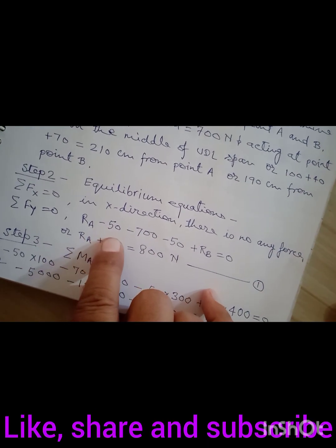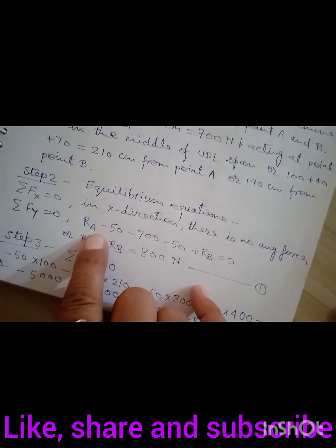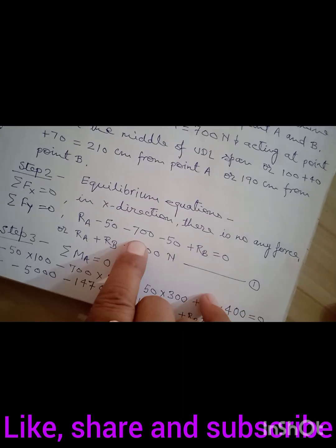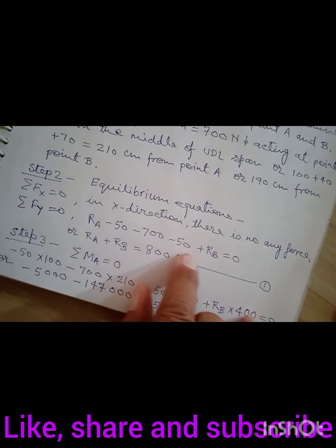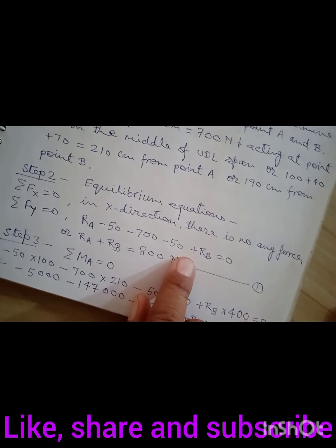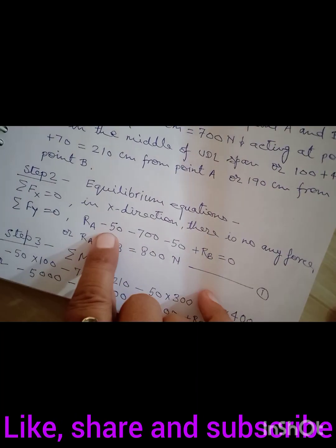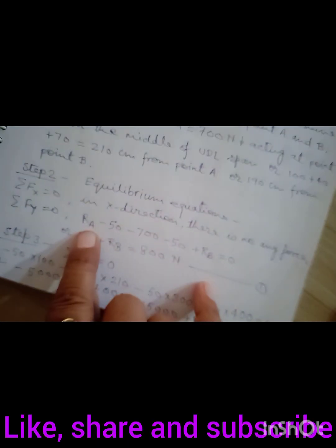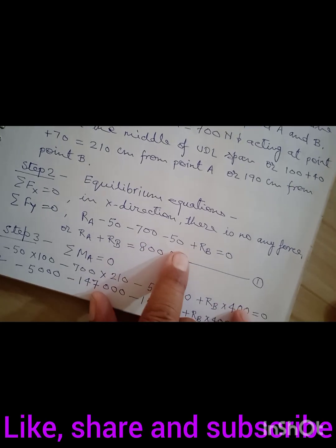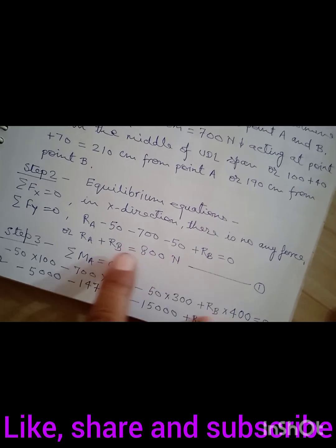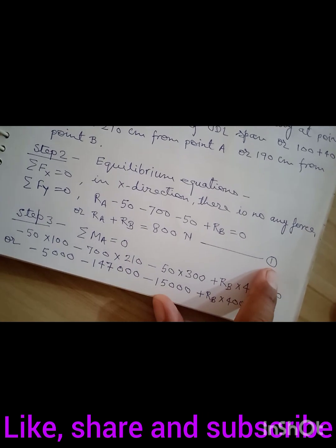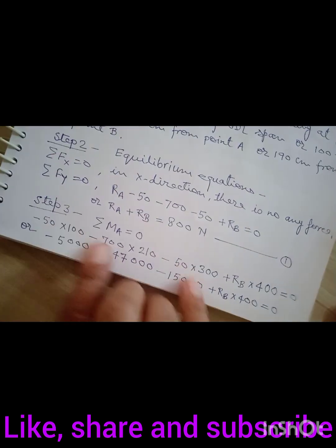RA and RB are both in upward direction, positive y direction, and 50 Newton, 700 Newton and 50 Newton, acting at C, E and D, are in negative y direction, so we take them as negative. Writing the equilibrium equation: RA minus 50 minus 700 minus 50 plus RB is equal to 0. From this equation we get RA plus RB is equal to 800 Newton. This is equation number 1.